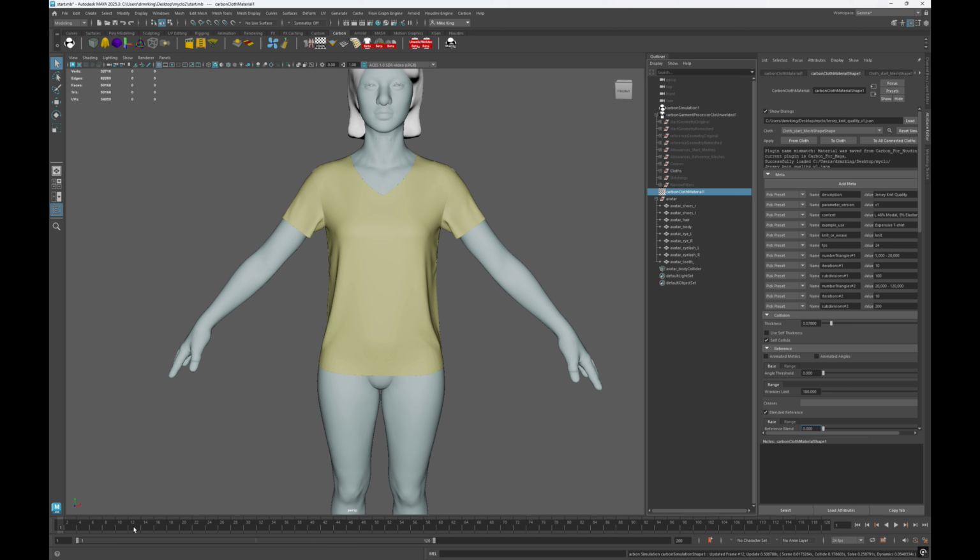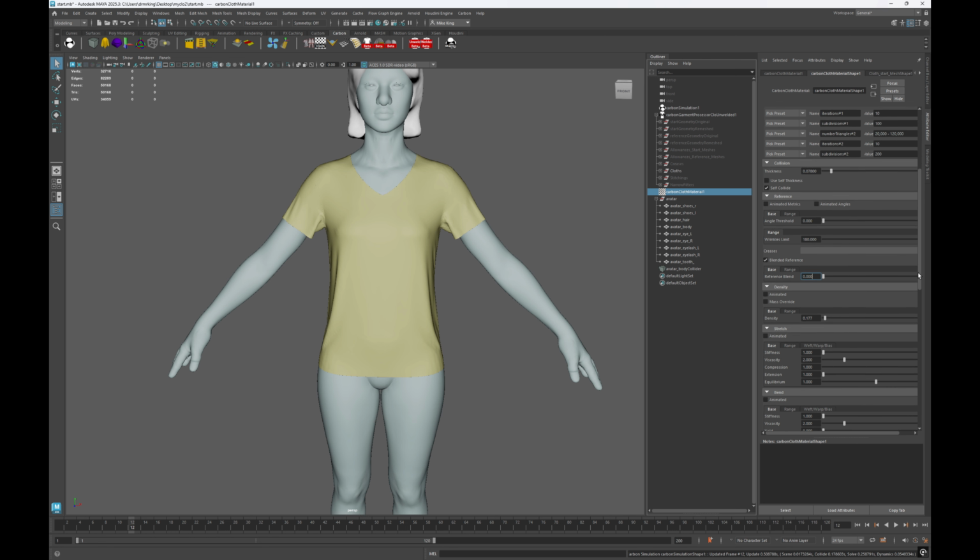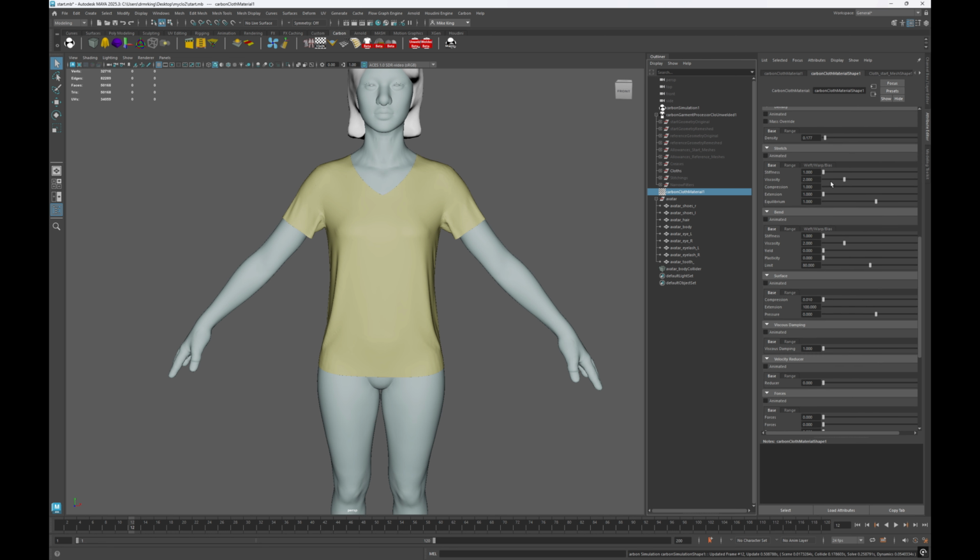It still stretches a tiny bit under gravity, and we can even remove that if you want by going down into the carbon material and just reducing the stretch extension from 1 to something a tiny bit smaller, so maybe 0.995, just 0.5% smaller.